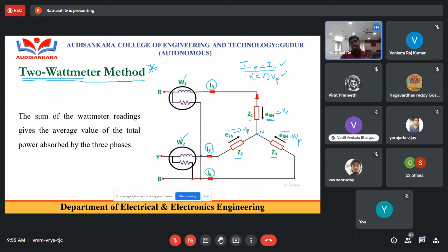You can connect a wattmeter to the R phase or B phase or Y phase, whatever it is. If you connect any of the different connections with 2 wattmeters, you get the same result. There is no doubt. For that, I am going to choose 2 wattmeters W1 and W2, both connected for phase R and phase Y.